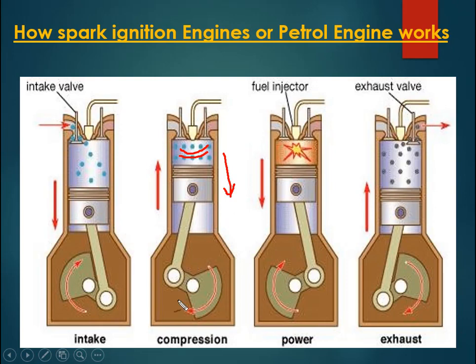But due to the crankshaft movement, the piston will try to push in the upper direction, and because of these two different direction motions, when the pressure front of the combustion reaction and the piston hit each other, a knocking sound is created, like a metallic sound.